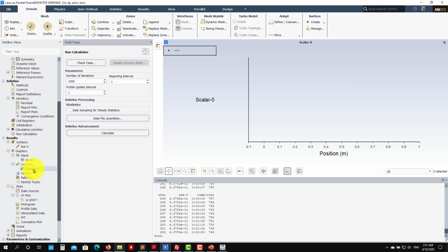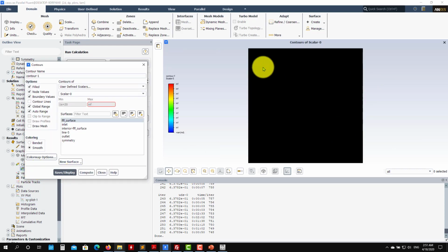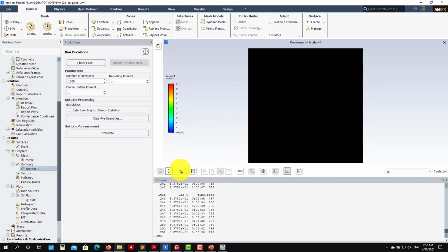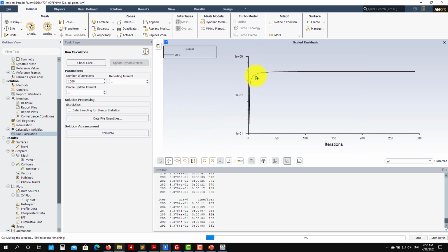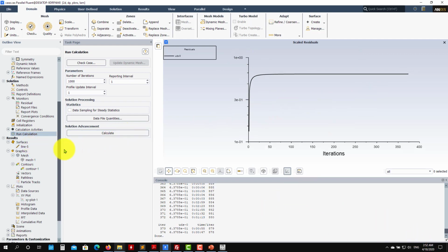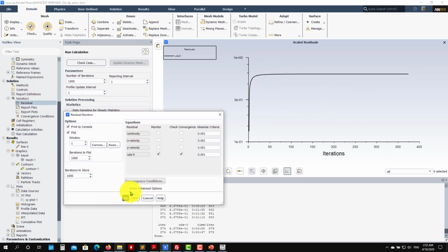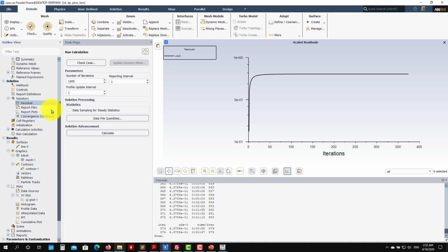So you can also plot. We haven't plotted solutions here. See that it's infinite, it actually diverged. And see that this is another problem. You are looking at the monitors here, and it's telling you that, okay, it is stalled, but it's not going larger than 1. But actually it's diverging. Your values are infinite, okay? So these are things that you don't see in this one. Again, another reason not to fully rely on these monitors.